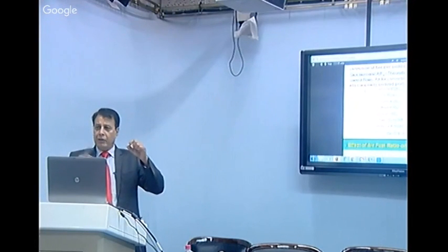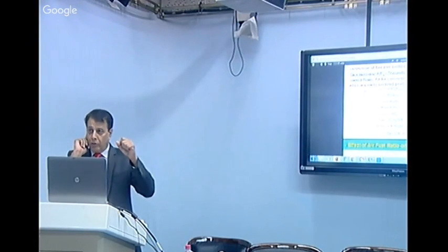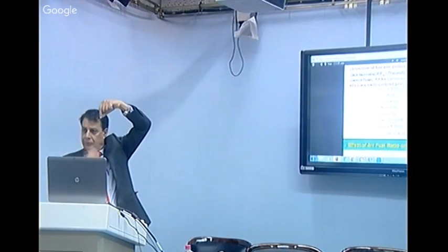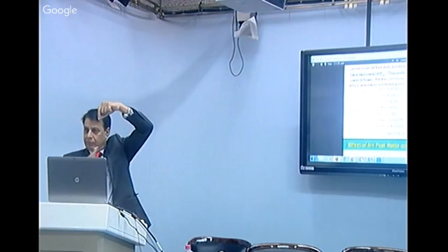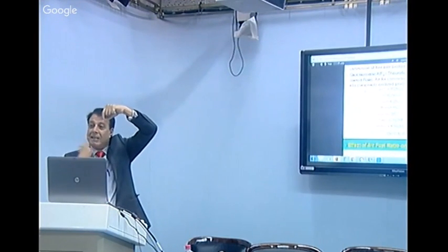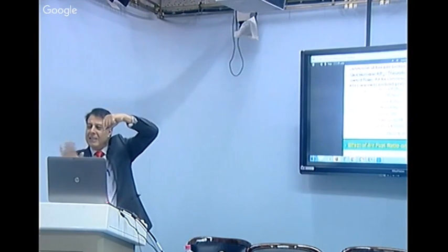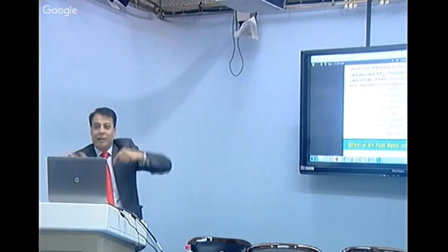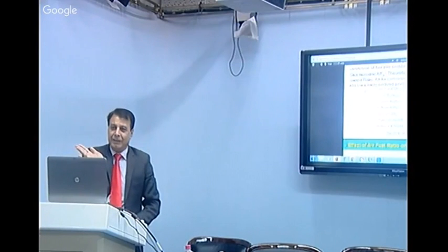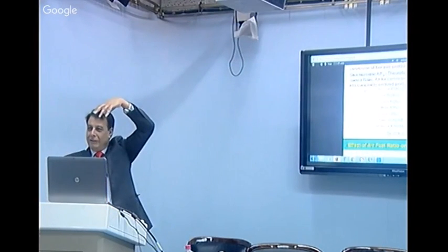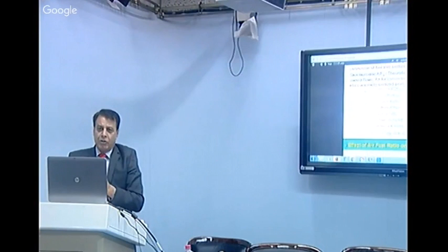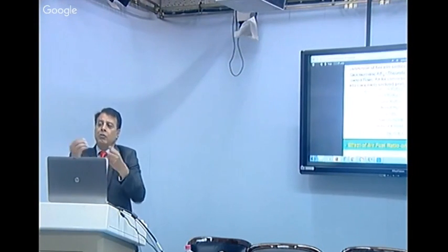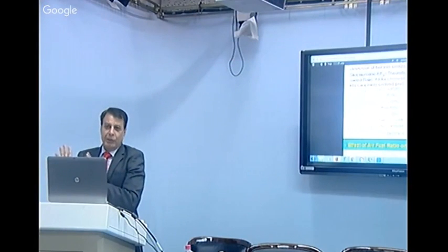So one thing we use is the cyclone. What does a cyclone do? It creates a swivel motion, and in that motion air particles can move and suddenly change direction. So air can change direction, but dust cannot do that. So dust is accumulated there only. Dust is separated out by the swirling motion of the air, without the media, without the air filter.